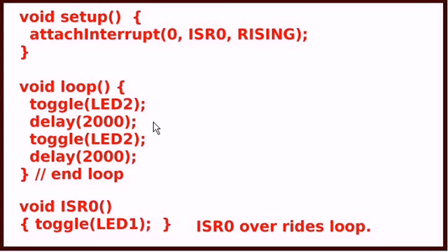It goes through its save the address and shut off the interrupts and that stuff. This interrupt service routine down here does its thing and returns back to that point where it interrupted loop, and it will go on. Now, the fact that you're using an interrupt-based routine like delay might throw the timing off. I'm not sure, but it probably does, so keep that in mind.